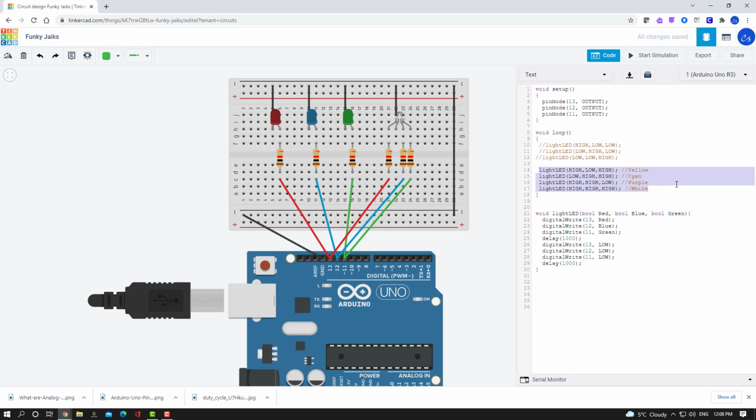This is a good natural breaking point for RGB lights, functions, variables, and everything else associated with this sketch. I highly recommend you play around with the code, see how you can manipulate these values to make some different colors, how you can change the delay statements to change the length, and even go as far as maybe getting a second LED, using different pins, maybe pins 9, 8, and 7, and having two color LEDs flashing in unison together or opposite colors at the same time.